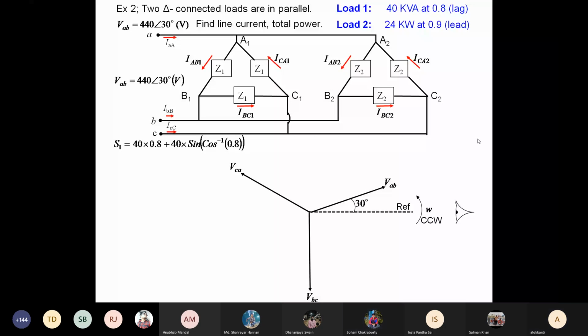Yes, sir. Okay, so you have to note down the steps, but it's not very difficult, because the mathematics we have already done, and you are all experts in sine theta, cos theta. We have just considered the power triangle. P and Q are the two powers, active power and reactive power, and S is basically the diagonal. So the first load is described by the S and the power factor angle, and from that you can find out P and Q.